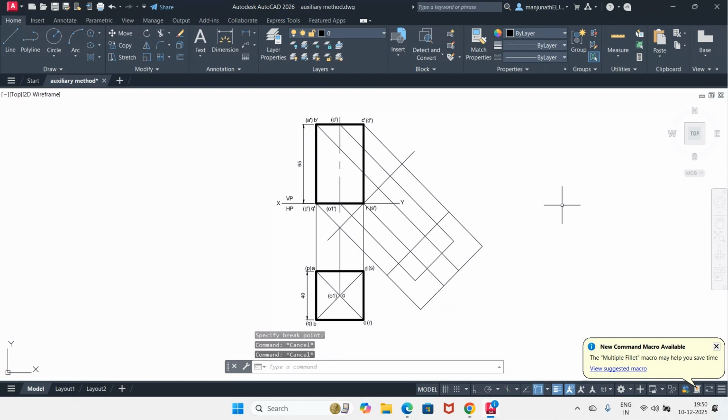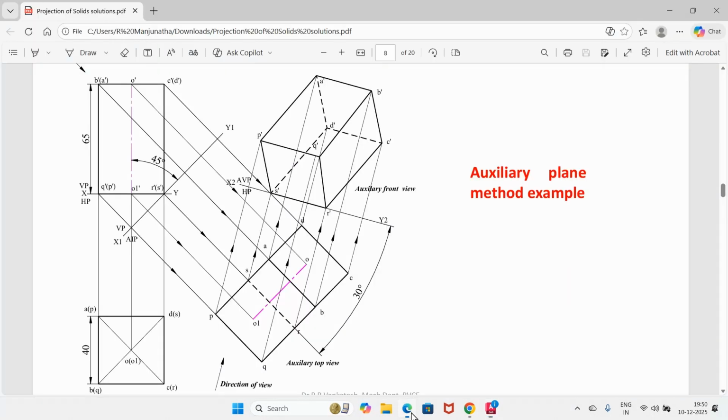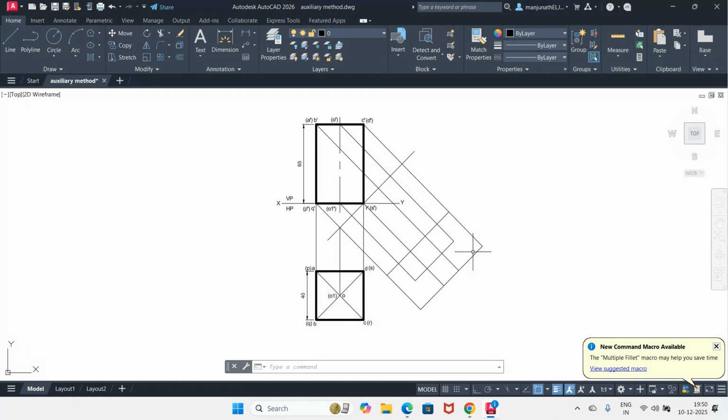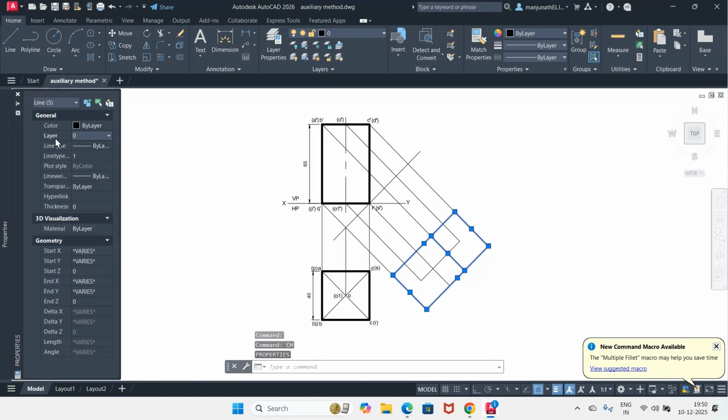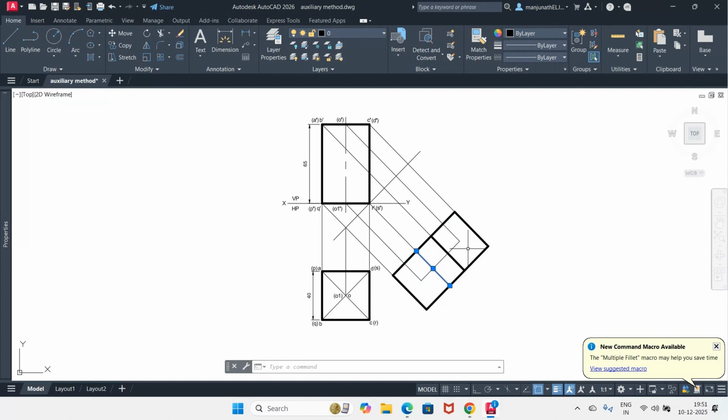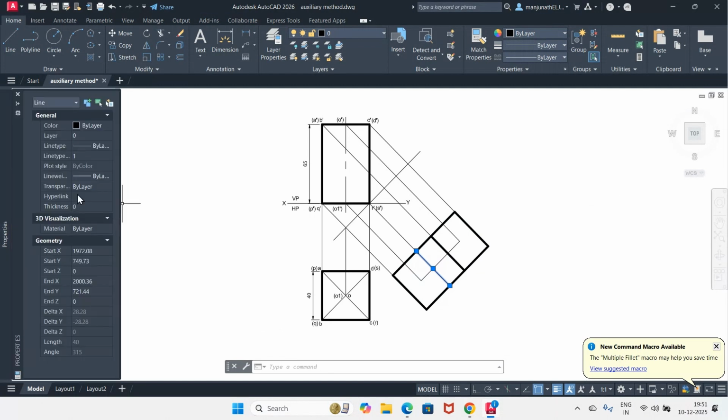Now we need to draw all the exterior edges, and then this line is dark, only this line is hidden, and this is the axis line. So to do that, I will select all these border lines, and then from here what I'm able to see is this. Go to CH, go to layer and make that layer as view layer. Come down to this, go to views and you click. Similarly, you select this and go to CH, go to layer, make that as the hidden layer.